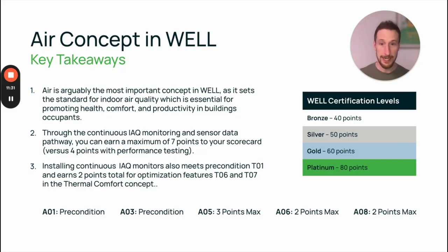Now, finally, installing continuous IAQ monitors gives you a lot of points under the air concept. I didn't talk about the benefits that are also under the thermal comfort concept. So air quality continuous monitors also allow you to meet precondition T01 and get 2 extra points under T06 and T07. So those are under thermal comfort. So if we add all of this together, the air concept and the thermal comfort concept, that's 9 optimization points and a lot of preconditions that are being met simply by having these continuous monitoring sensors on the walls.